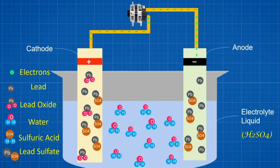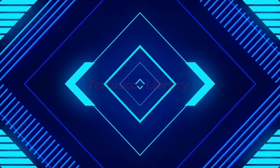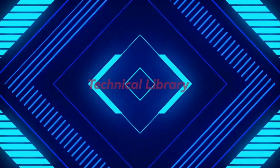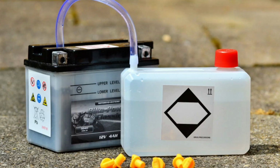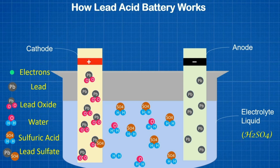How does a lead-acid battery work? In a single cell there are two terminals, one is positive or cathode, which is made of lead oxide, and the other is negative or anode, which is made of pure lead. The cell is filled with diluted sulfuric acid. That is also called the electrolyte.